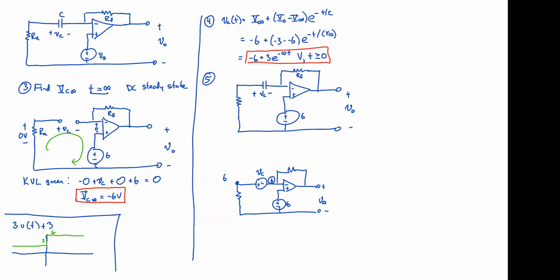The way that the signs are defined, it's saying that the left side is higher than the input. So this would be 6 plus V sub C. We don't know what V naught is, though, because there could be current flowing through this resistor, and we don't know what it is. Or do we? Do you see how you could tell what that current is? We said this is R sub A. Wouldn't it be 0? Why would this current, we'll call this I sub A, be 0?